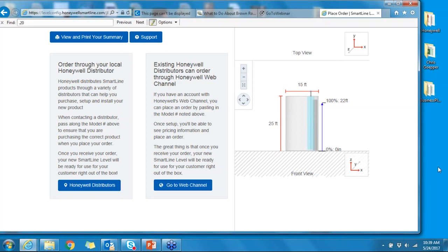Let me back off here. Let me make a correction. It won't be totally configured. When you get to the tank, when you set it up and you start it, the first electronic pulse will tell you exactly where the level is at that time, and then you will set up the unit once it determines where the level of liquid is in the tank. So there is some setup required, because you never know when you install a unit what the level of the liquid is in the tank. Right, but it's minimal. You don't have to go through and program the whole thing. That's correct. The installation is done on PACTware, which is a free software.